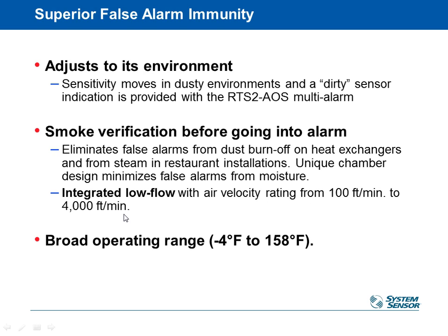They do have the ability to calibrate themselves, or adjust themselves, I should say, for the amount of dust in your system, so you get fewer false trips. You eliminate some of that dust burn-off when you fire up your heat exchanger for the first time, so you don't get those kinds of false alarms, and you don't get false alarms related to moisture problems like steam humidifiers or cooking in a restaurant or something like that.